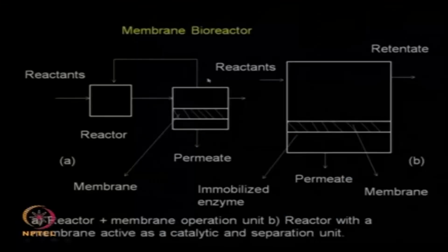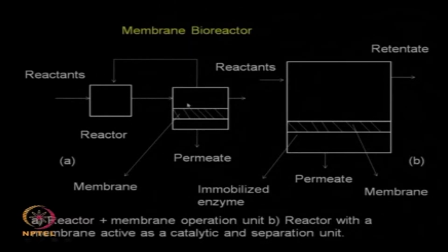So in a normal conventional fermentation we just stop the reaction, but if I have a membrane I can continuously remove part of the alcohol that is produced and the remaining active biomass can be sent back. So the advantage is the concentration of the alcohol will be much lower all the time in your reactor.